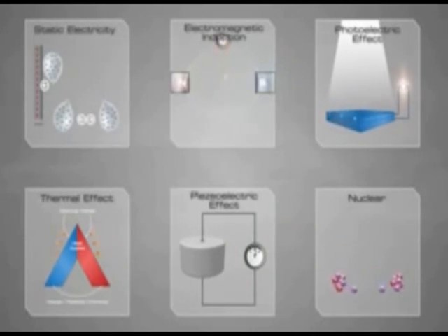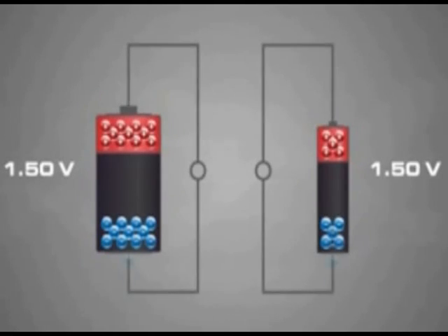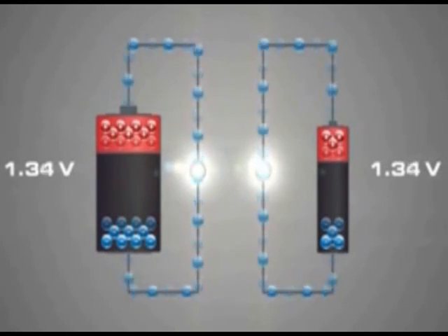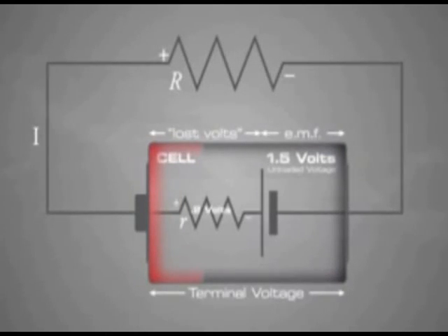The potential difference across 2 open terminals is known as the unloaded voltage and is equal to the electromotive force of the cell. This EMF forces current to flow when a circuit is attached to the source of EMF. There is typically some amount of resistance in all electrical components and devices. When current flows, the voltage across the terminals of the source of EMF is no longer the unloaded value. There will be a voltage drop inside the device due to the internal resistance of the EMF source.